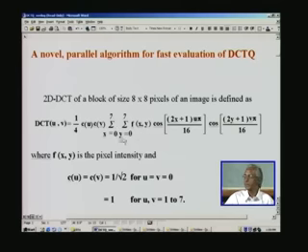If you do that, sigma is for summation, and if you apply it for this alone, it simply implies the summation of all the pixel intensities. To keep it simple, let us deal only with one component, one color component, or just a plain monochrome. And if you are processing color, we are dealing only with one of the components, either Y or CB, CR.